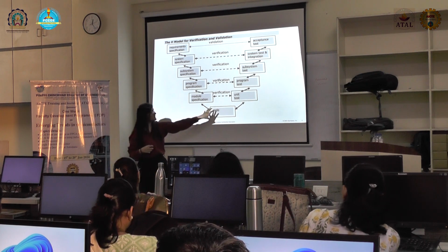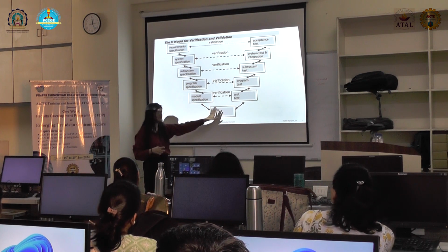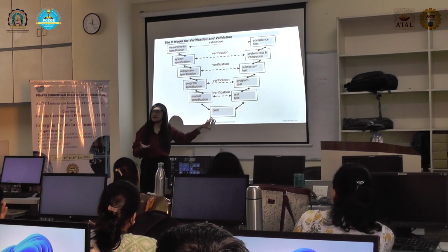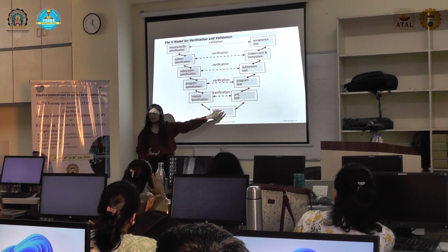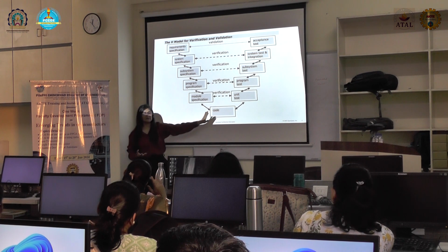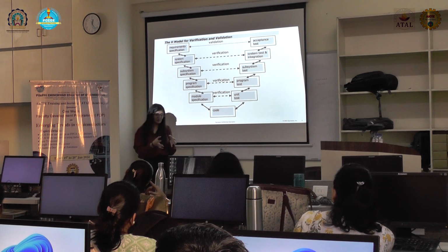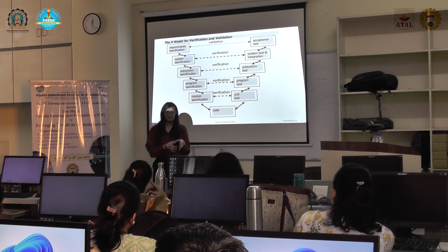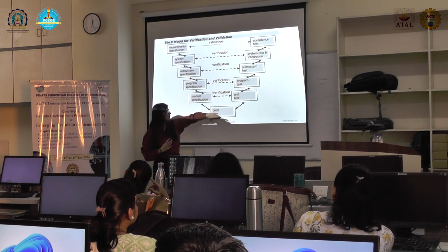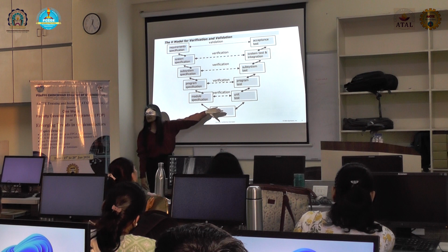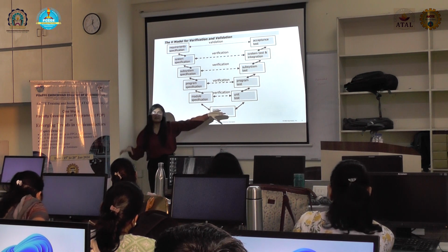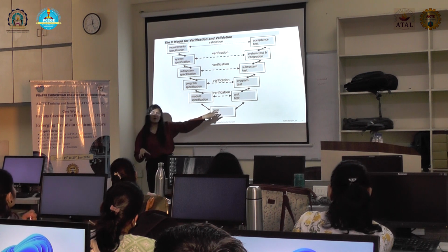And the base needs to be our code. DUT is design under test. So whatever we are building is on the DUT. Here, in design review, we micro-analyze the design. But for verification, for a verification engineer, this is a black box. We don't check the code of a design unless we are debugging deep.